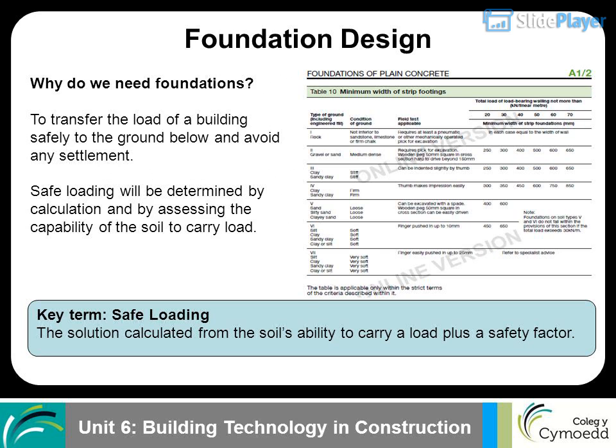Foundation design. Why do we need foundations? To transfer the load of a building safely to the ground below and avoid any settlement. Safe loading will be determined by calculation and by assessing the capability of the soil to carry load. Key term: safe loading. The solution calculated from the soil's ability to carry a load plus a safety factor.